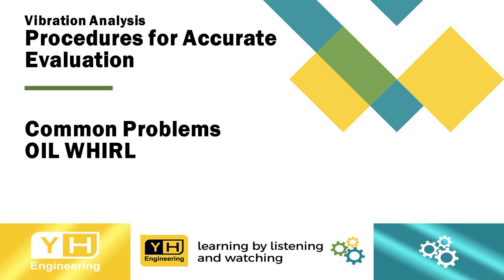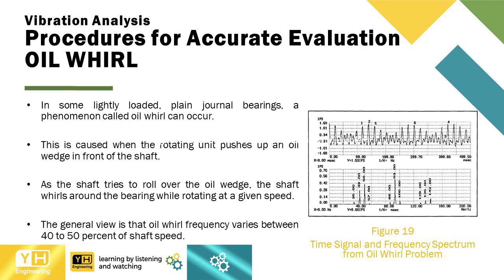Vibration analysis. Procedures for accurate evaluation of machinery condition. Common problems. Oil whirl. In some lightly loaded, plain journal bearings, a phenomenon called oil whirl can occur. This is caused when the rotating unit pushes up an oil wedge in front of the shaft.